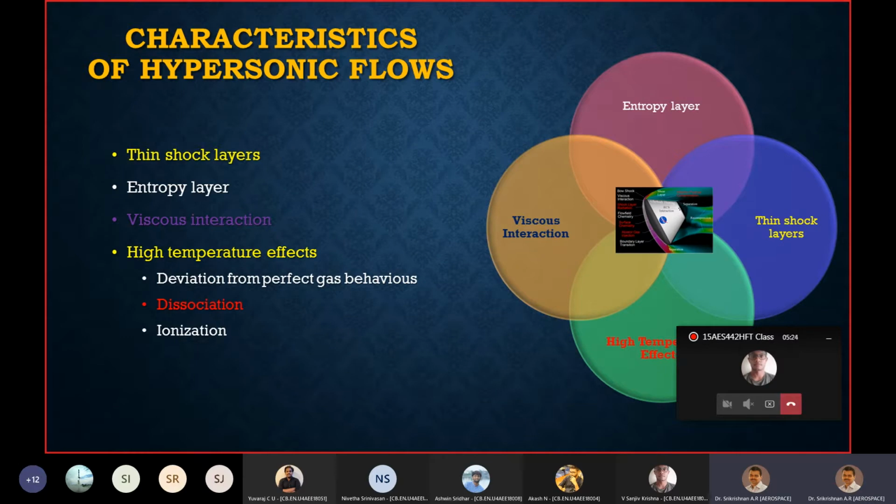So only beyond the atmosphere, where the density becomes gradually lower and lower, the rarefaction effects become important. Since in such situations you have hypersonic vehicles as well as rarefied gas, you have to consider the combination of the two. But otherwise, in hypersonic flow, rarefaction cannot be considered an inherent part of it. It happens only when you go beyond the atmosphere.